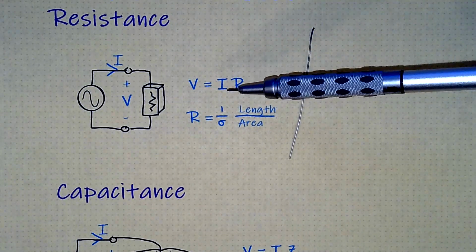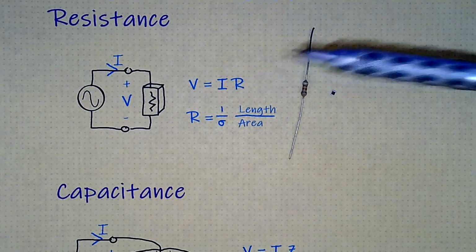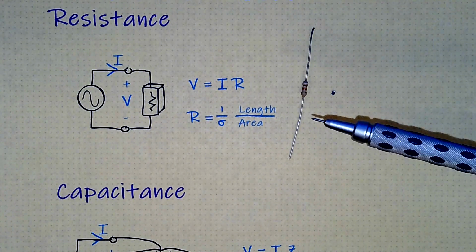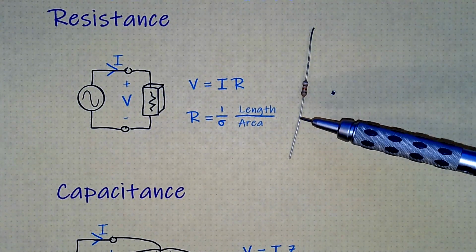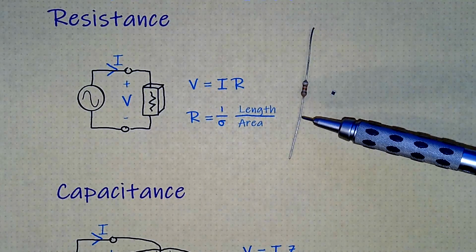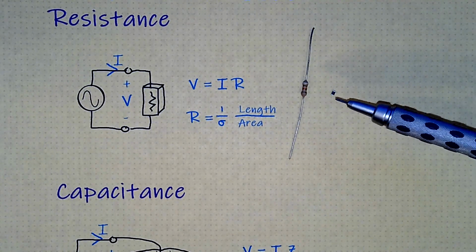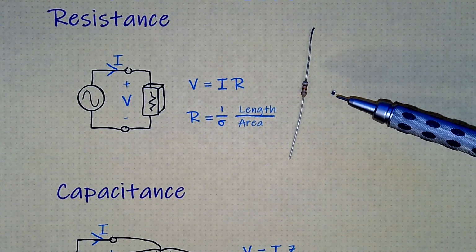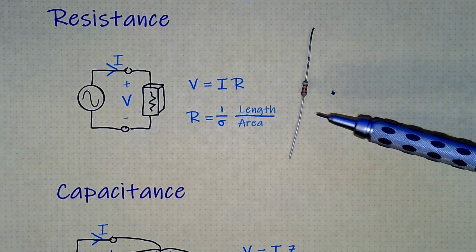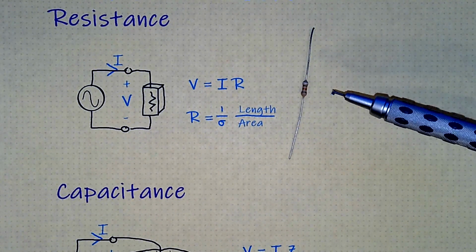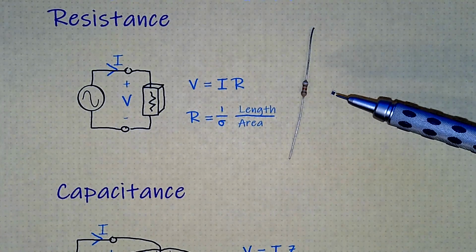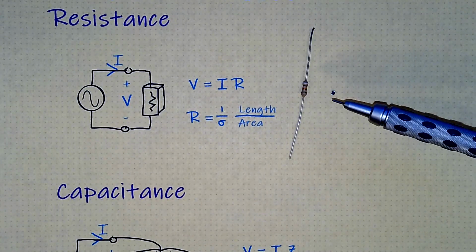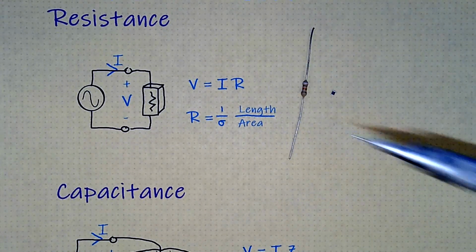Now, this is the ideal behavior. At high frequencies, at radio frequencies, these leaded resistors can become real problems, as we'll see. That's one of the reasons that we went to surface mount, although another one was to reduce the size of the electronics. To understand, however, that even the surface mount ones have some limitations, we need to look at capacitance and inductance and then come back to the resistor.